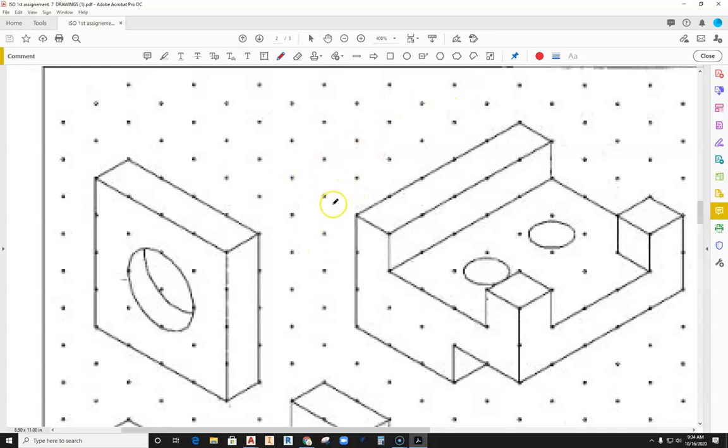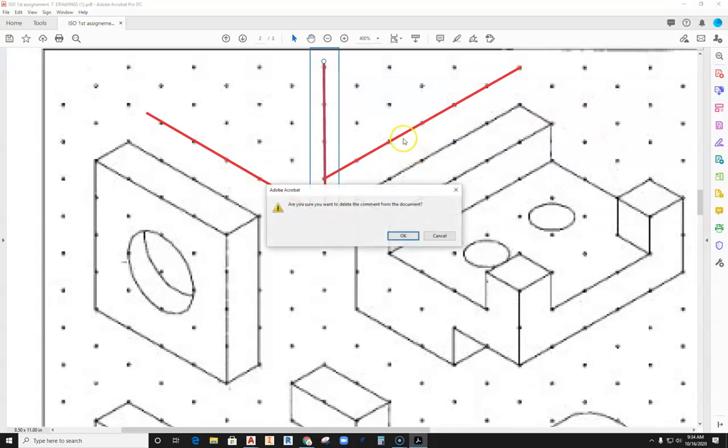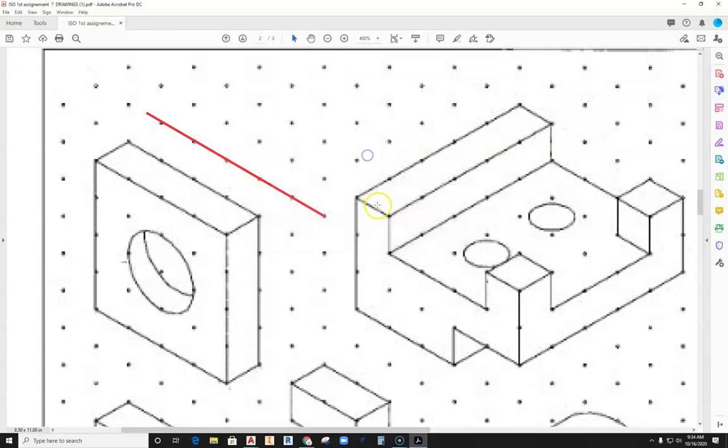But when it says each dot is ½ inch away from each other, what they're talking about is along the isometric axes. So this is an isometric axis. As I draw back here, that is an isometric axis. There is another isometric axis right here. So this is an isometric axis, and so forth and so on. Another isometric axis is then the vertical axis. So you can see that these things line up on the isometric axes. Think about the isoplane right, isoplane left, and isoplane top.